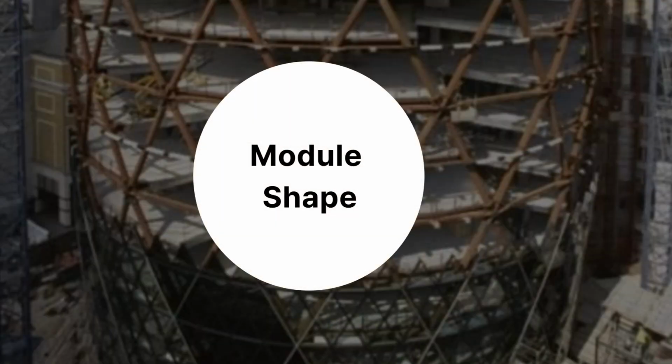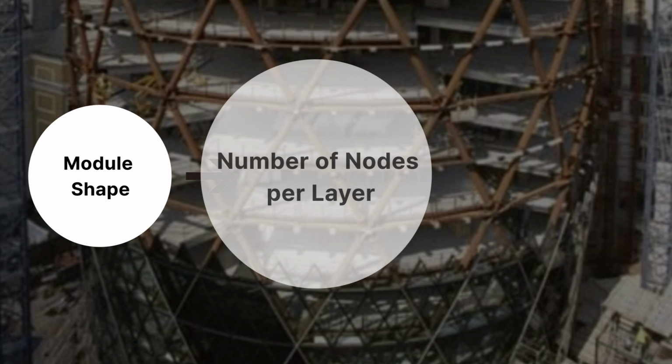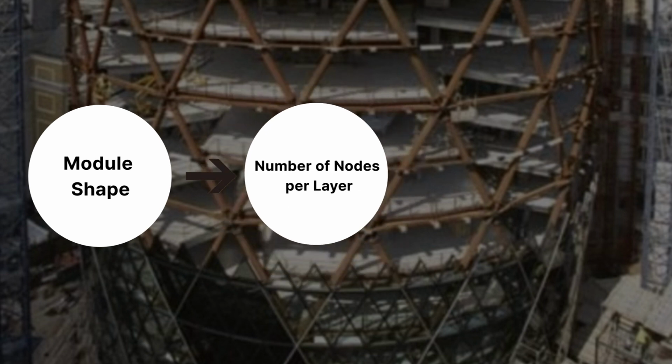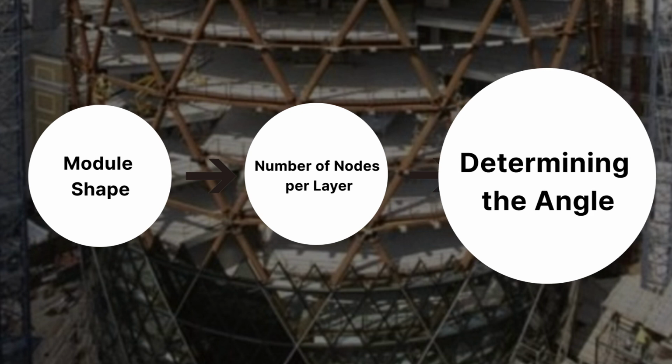After deciding the shape of the diagrid module in the building, determine the number of nodes on each floor according to the shape of each module and the height of the building. Then select the optimal angle within the possible angular range to determine the appropriate angle between each node.